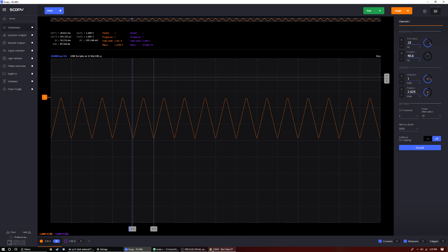But as we can see, that cuts the frequency down to like 97 hertz. That's not ideal. So in the future, if I were to do a project like this again, I would spec out the frequency of the clock onto the PWM, and also do some math to calculate how fast the PWM can go before I get started.